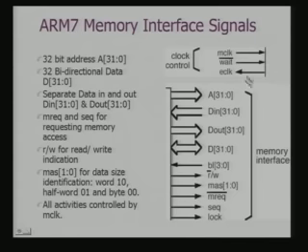Now, here you can find that the clock control has associated with it a signal called wait bar. This is an active low signal. In fact, your internal clock for the processor core is a combination of the two. And how and where to use this wait signal? If you remember, I said that in many cases my memory may be slow.